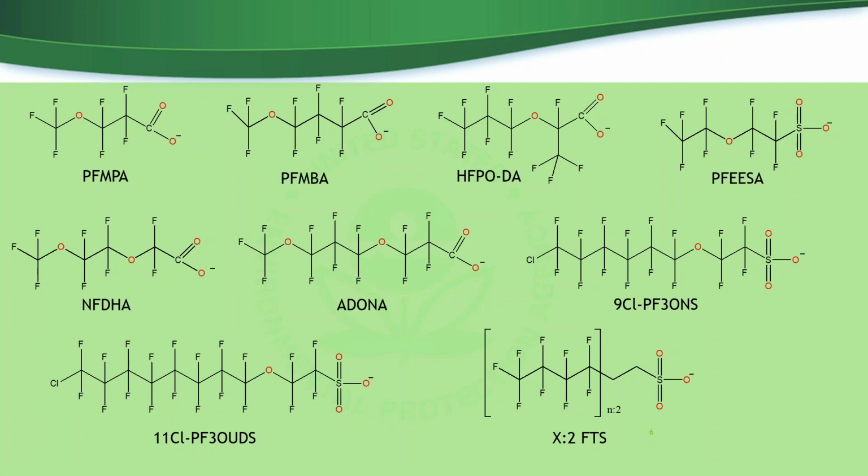Yeah, EPA is working on methods beyond drinking water. There is a direct injection method that just closed for comment, that is available for non-drinking water aqueous samples. For the solids, we're working with a number of partners, including DoD, to accelerate the methods development effort. It will likely go through both Clean Water Act and SW-846, so there'll be two options for those solids methods as they come along. We're probably looking at something in the 12-month time frame at the earliest before those get out and promulgated.